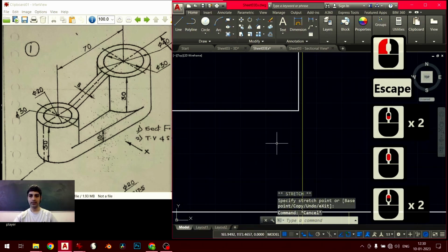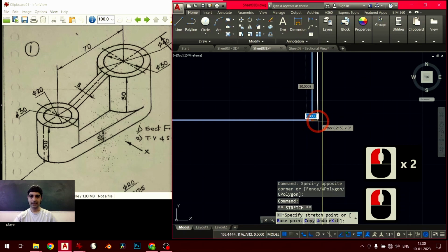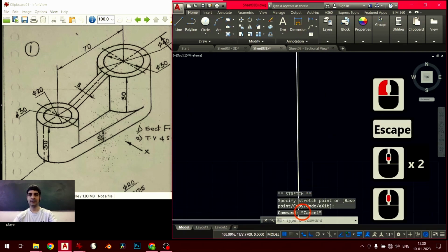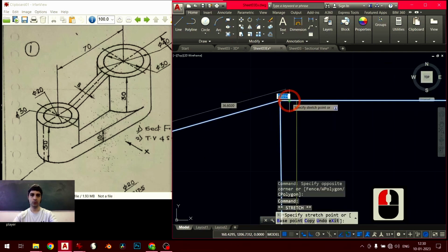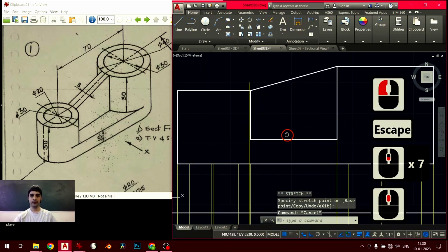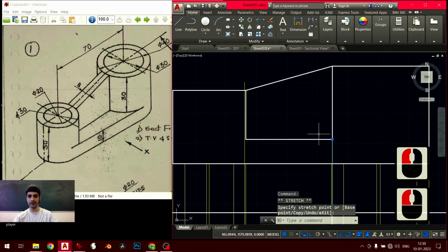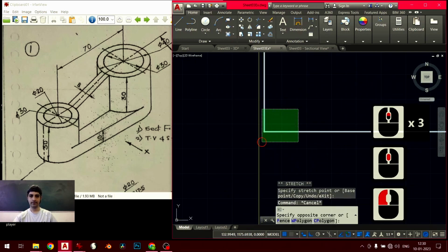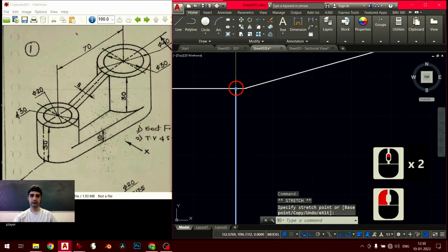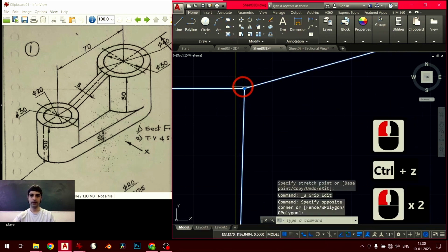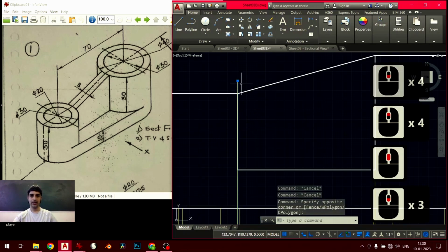and then what I can do is I can take these two lines. I'm just making a green line around them, and then I'll take this corner and snap. I do the same thing for these three at the top here. I just make sure they're selected, and then I'll take this little blue grip and snap it here. I'll remember then to just reduce the length of this projector all the way down because you don't want these lines overlapping. And then I'll do the same thing on this corner as well. Once again, I'll select the whole thing and then I'll reduce this.